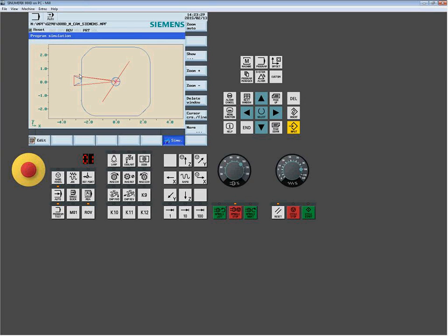you're going to start to see the machine come around. It's applying some form of cutter compensation. Okay. Now, this is the first area that you have to start to pay attention to when you roll around the cutter comp. What's right now and what you don't know, which I already know because obviously I methodized all this stuff, is that we think that the machine should be running tool 1. The way the parameters are set up in this machine, it's in the offset based on the T code, not necessarily the M6.